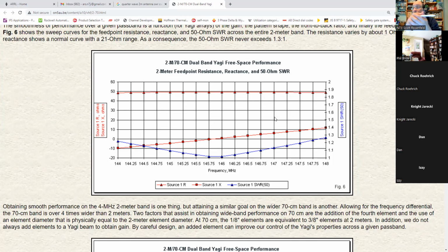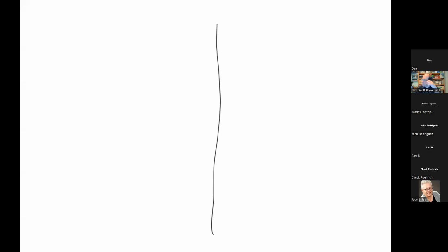This is actually how you would, for instance, if you have a commercial AM radio station with a grounded tower, have one connection going to the base and the other connecting some distance above, so that because you're at a given frequency, it's not actually shorted out.